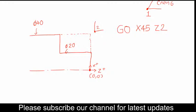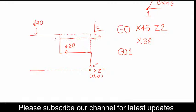Now, since we start to cut, we have to move from point number 2 to point number 3, and for that we have to write X38. Up till now it is X40, and then we will be lowering down by 2 mm, so it is 40 minus 2, that is 38. Now we have to write what? G01.